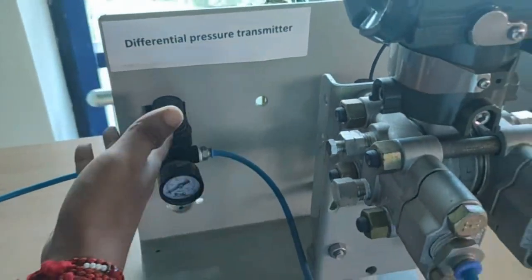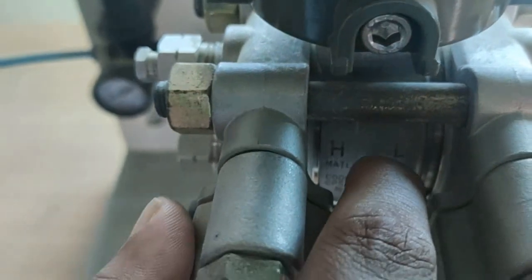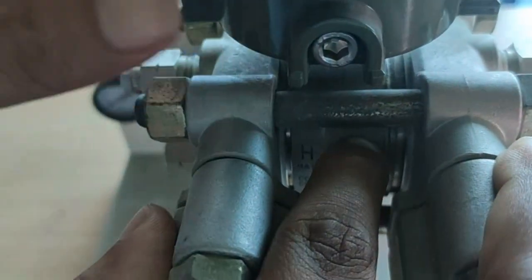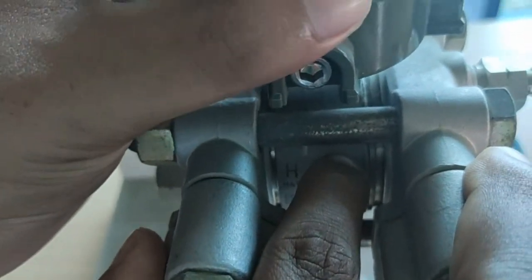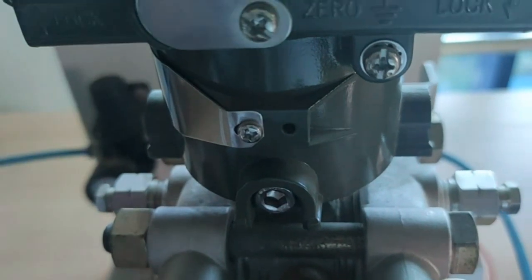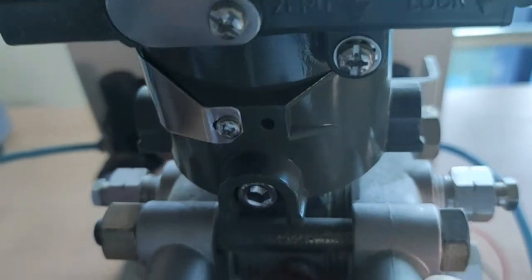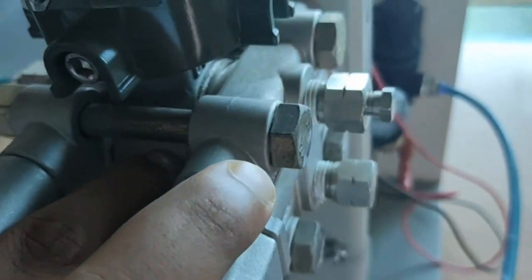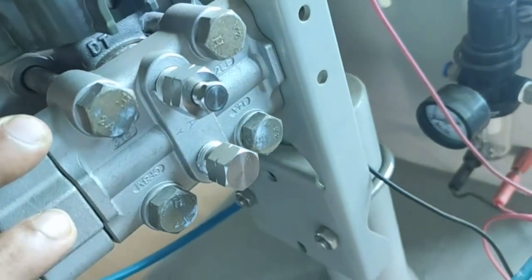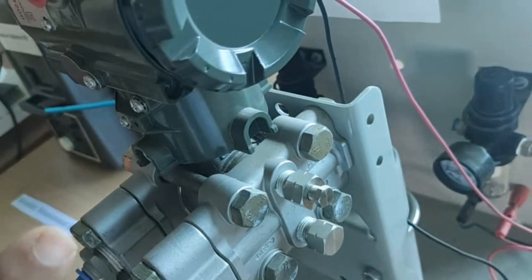So due to this change in pressure, which is measured by this instrument, the pressure drop is sensed by the diaphragm element situated in between, and further it is processed using maybe a strain gauge or any other electrical component, which is processed and amplified, and we will get the output as a 4 to 20 milliampere current signal, right? So this is the whole procedure of the differential pressure transmitter.